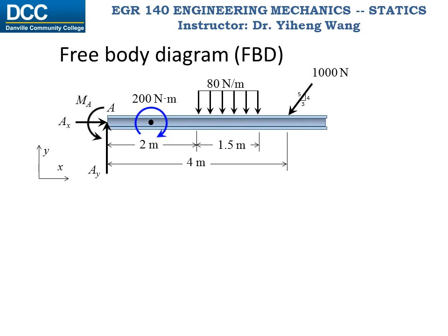Since this is a 2D problem, all motions can only occur within the xy plane, therefore there cannot be any other type of motion, and the wall will not provide any other type of support reactions. Now the free body diagram is complete, and we have exactly 3 unknowns, Ax, Ay, and Ma. Therefore, we can write the 3 equilibrium equations to solve for all of them.